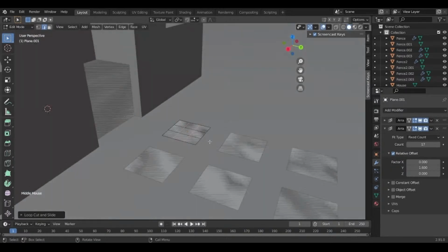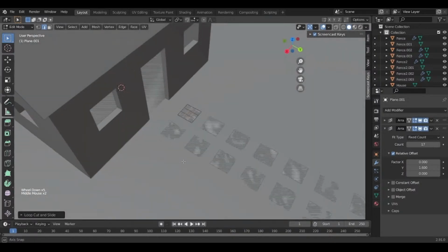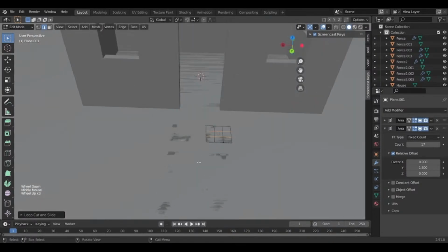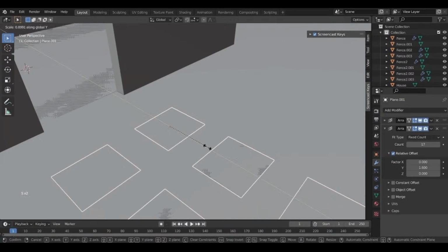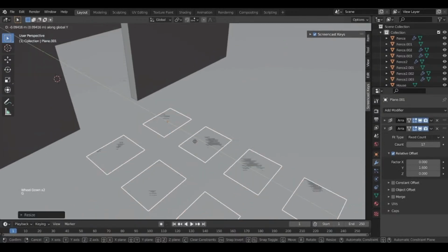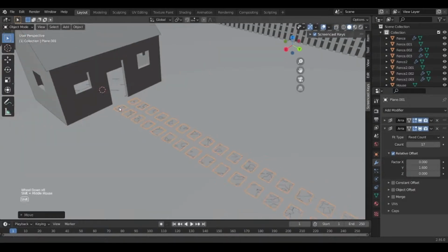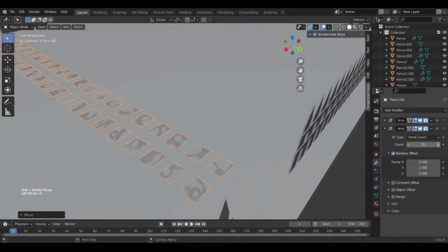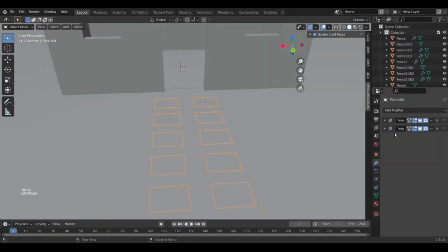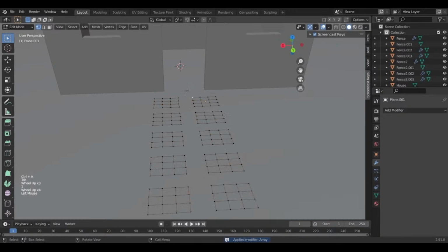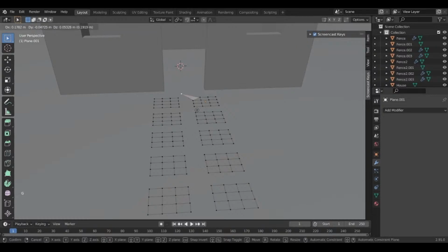This will be rocks, so when I randomize them, you will get why I'm adding more geometry here. This process will be a bit tedious, but it is what it is. So I'm just gonna apply the area modifiers, and then select, so I'm going to show proportional editing. If I move this vertex, it will just move on its own and then reshape, right?